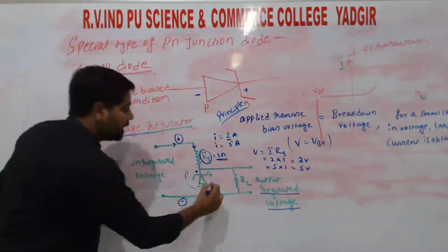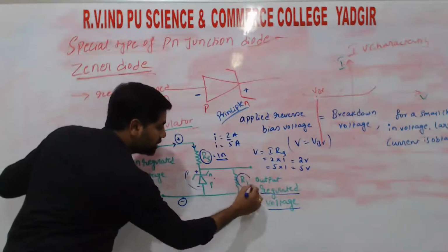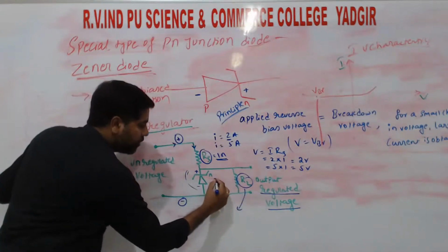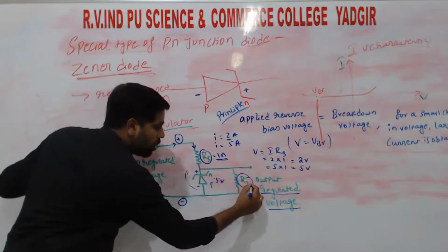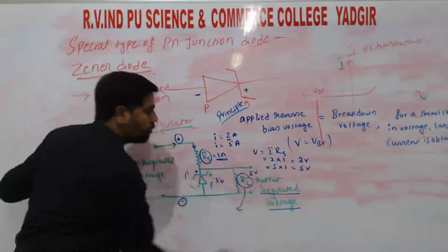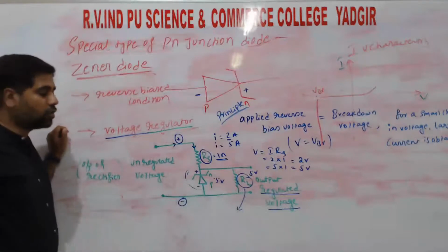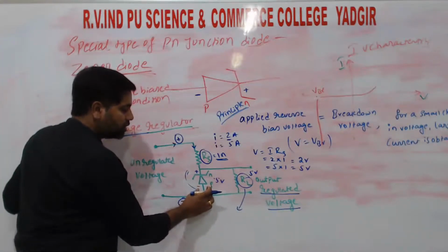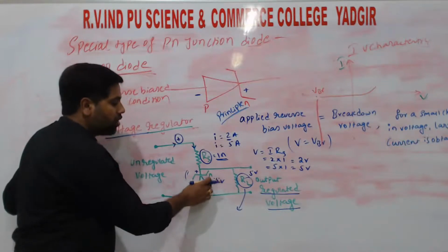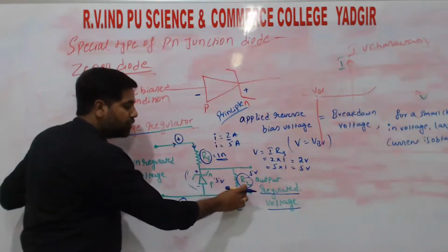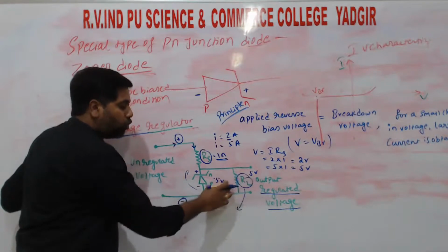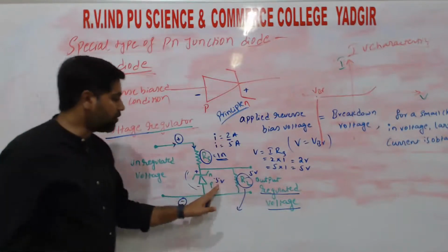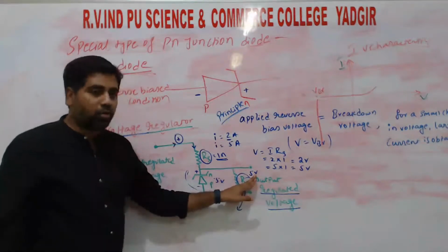That means we are getting the regulated voltage, right? So for example, across this load resistance, because these two are in parallel, if we have some 5 volt here, then across this load resistance also 5 volt, right? Understanding this, the voltage across any conductor or any diode which is in parallel with another is the same for both. So here 5 volt means here also 5 volt, right?